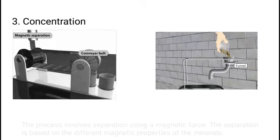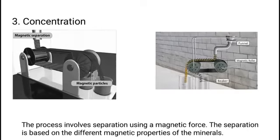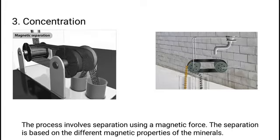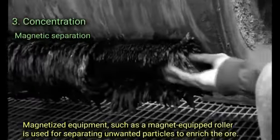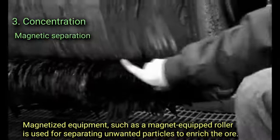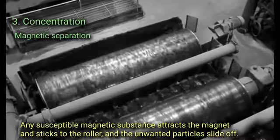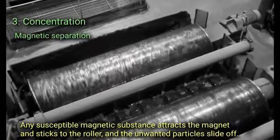Magnetic separation. The process involves separation using a magnetic force. The separation is based on the different magnetic properties of the minerals. Magnetized equipment, such as magnet-equipped rollers, is used for separating unwanted particles to enrich the ore. Any susceptible magnetic substance attracts the magnet and sticks to the rollers while the unwanted particles slide off.